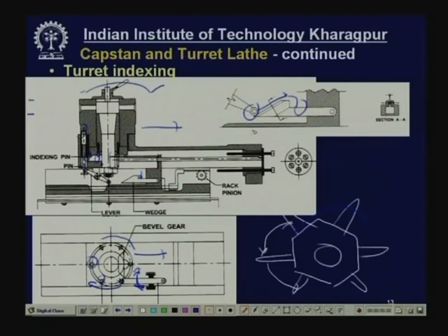After that, when you move forward, you again rotate this pinion by a lever, and then this will go forward, and this roller will come through this big hole, just like a T slot. So, the roller will ride on the surface and come through this larger gap provided here as shown here. But how far will it go? Now, when it goes forward, this forward movement can be accomplished either manually or automatically by engaging a clutch.